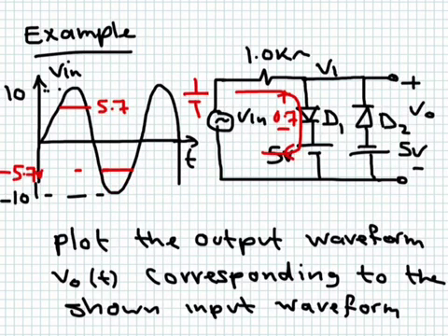Where does the rest of the voltage go? This is minus 10, say. If you have minus 10 between this point and this point, where does the rest of the drop go? It will go across this resistance here. This resistance will absorb the remaining drop, and the current in this case is flowing this way, because it's a negative supply voltage.